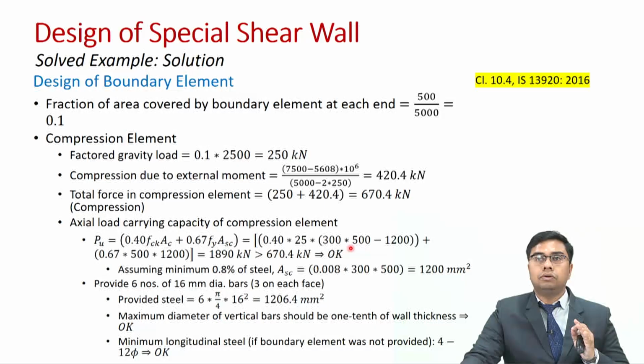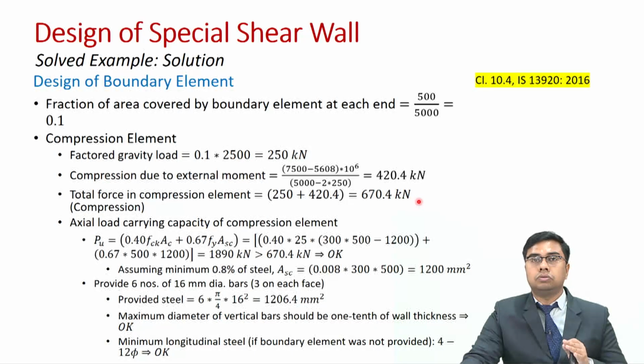I hope this is clear to you, and once we have found out the axial load carrying capacity, this capacity is more than the total force in compression. So which means our section is suitable and safe. Now we also need to satisfy some ductile detailing requirements. What are the ductile detailing requirements?